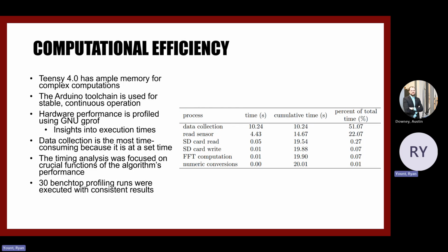So obviously, we used a specific microcontroller for this. We used a Teensy 4.0, and we used that because it's useful for continuous structural health monitoring because of its large amount of memory for complex calculations. And then we also used the Arduino toolchain because of its simplicity and use with the Teensy.